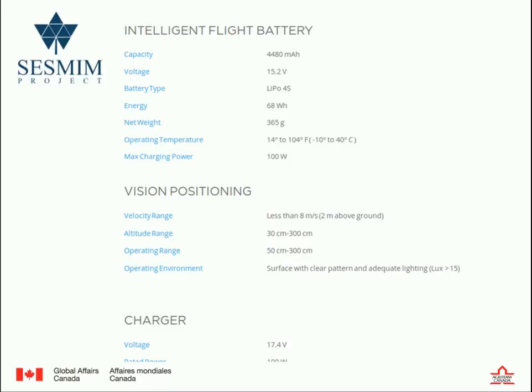So if you're going to China, this is well under the maximum you can carry on a plane. So you're okay. The other difference I forgot to mention, although it's the same battery: on the Phantom 3 Pro, you have a charger of 100 watts. And I think on the 3 Advanced, it's a lower wattage, so it takes more time to charge the batteries. So the Phantom 3 Pro charger will charge up the same batteries faster than the Phantom 3 Advanced. That's all.